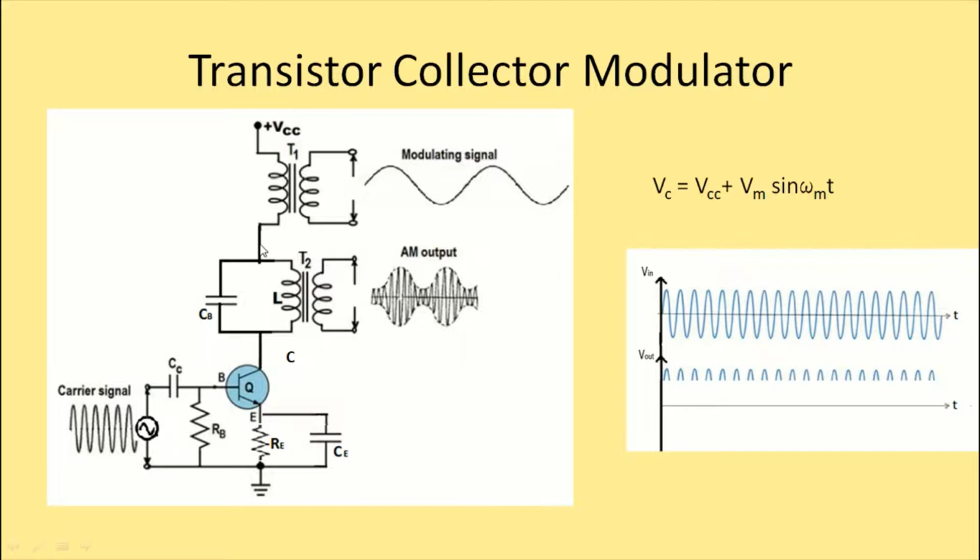So now you can see that when compared to the previous level of biasing, the current biasing is slightly reduced. The previous condition we discussed was at VCC plus 5 volts. The current condition is VCC plus 3 volts. So that means the amplitude of the spurt is now slightly reduced. And because of that, the amplitude of the sine wave generated here is also slightly reduced. So it will be this region of the envelope at this point.